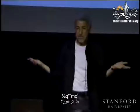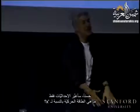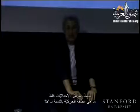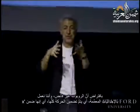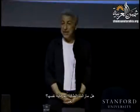You agree? All right, I just changed my coordinates. What is the kinetic energy described with respect to x dot? Supposing the robot is non-redundant, and these are generalized coordinates, so they capture all the motion, so it's in x dot. So what would be the kinetic energy? 1/2 x dot transpose Mx x dot. You agree? Is it the same kinetic energy? Yeah.